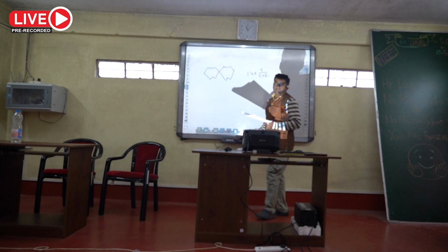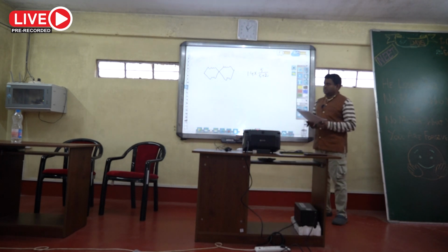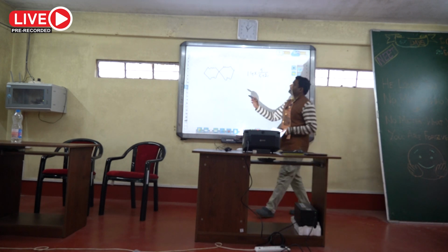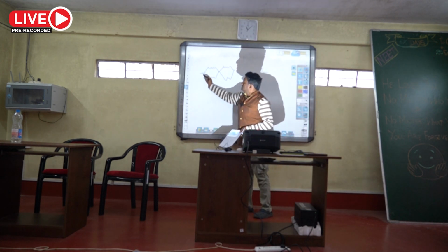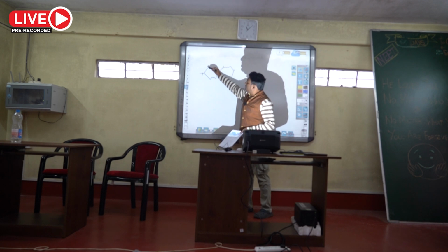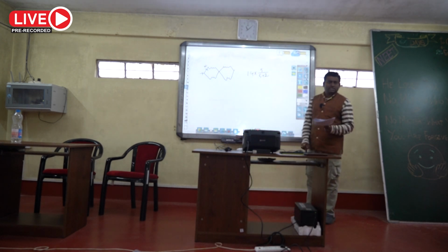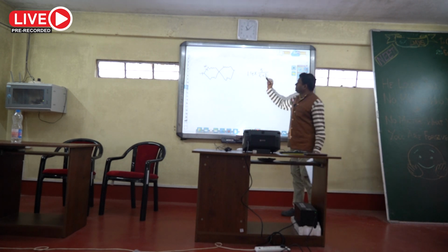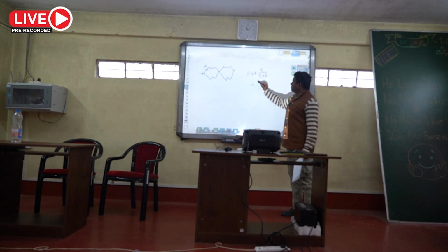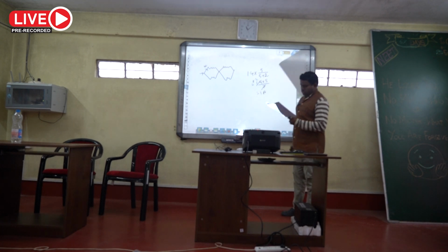After removal of the bridge resistance, the current entering here is divided into two parts. The current flowing through this part that we want to calculate will be in the inverse ratio of the resistance. That will be 20:50, which means 2:5. So the inverse ratio of the resistance is this one. So it will be 1.4 into 5 divided by 7. That is 0.2 into 5, that is 1 ampere.